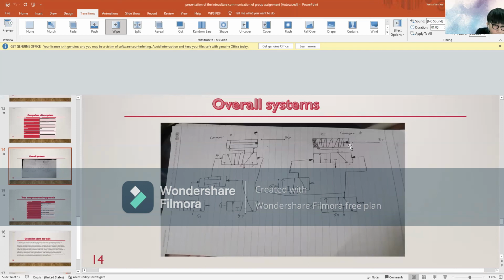So when conveyor B is clamping the product and it senses S4, the sensor will sense it and act as a push button to push back the piston, and at the same time it also pushes back the 5/2-way directional control valve, so that both pistons go back at the same time.